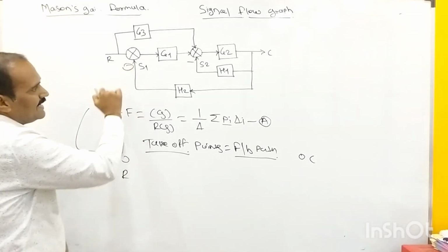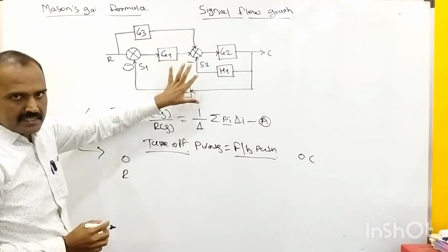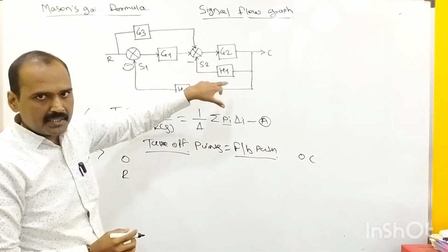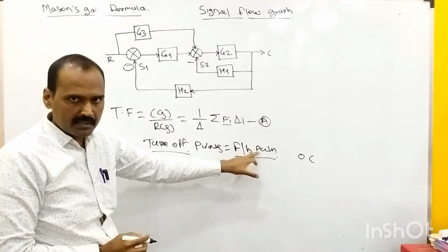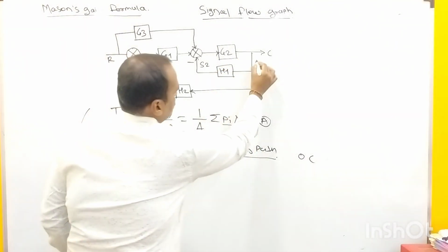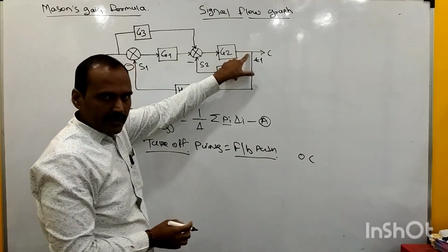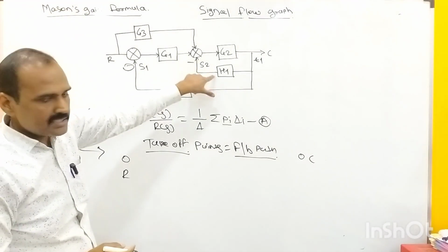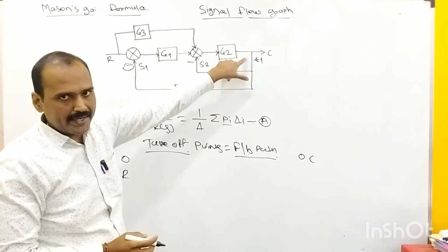So this negative sign indicates that negative feedback is to be adopted by this system, right? Here, as we have these two feedback paths, as I told you earlier, the number of takeoff points equals the number of feedback paths. But the unique identity belonging to this takeoff point, if we call it T1, is that within the same takeoff point there will be the significance of H2 as well as H1. Both these feedback signals are given with this takeoff point, right?